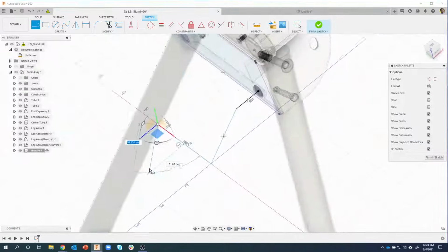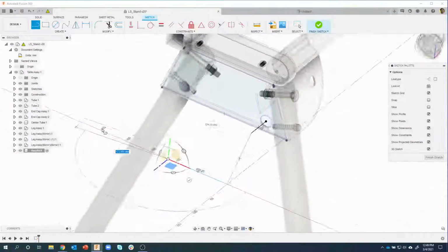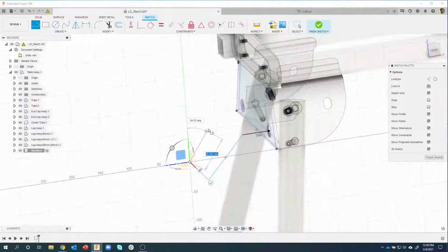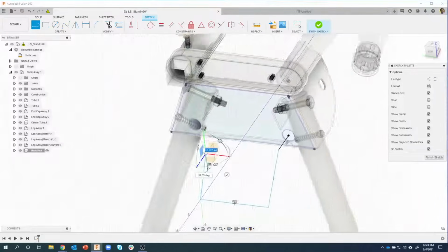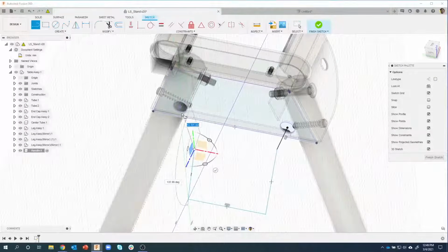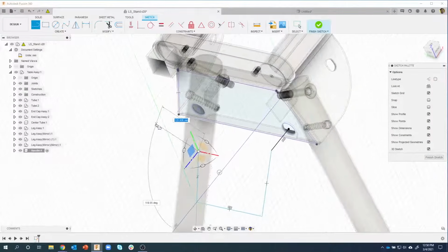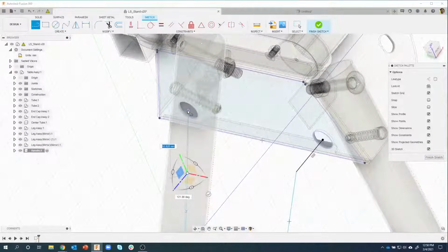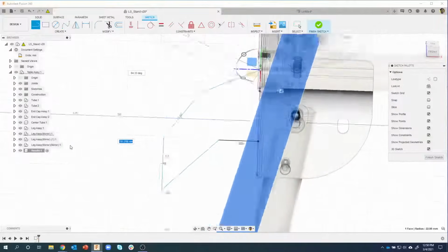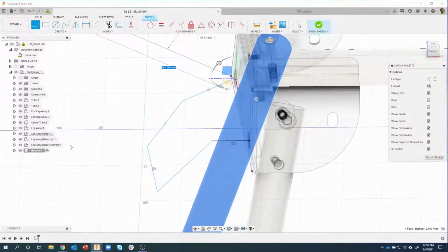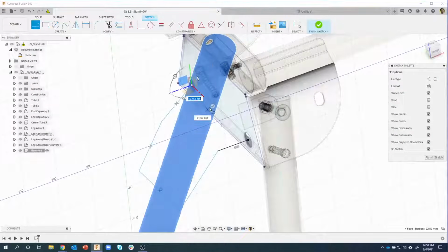See how it's starting to look, it's hard to see, but it's starting to look like we're drawing in 3D. Then I need to go back up again. So let's just go up like so. And again, I'm purposely making mistakes here to fix things. And then the last thing I want to do is close out at this point right here that we projected. There's a little circle there, so I'm going to click on that guy. And we can see our 3D sketch using the line command. Now I'm done, so I'm going to hit this green checkbox.